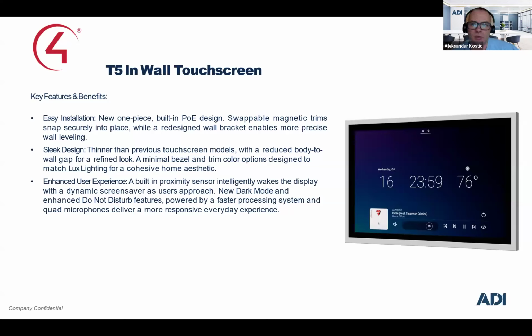You can order T5 in two main colors, black and white, but you can additionally order an extra frame in some other color to match your interior design. At this moment, those frames are available only as plastic frames, but we expect to have metal ones in the future as well. So just have in mind that if you use metal frames later, you cannot use Wi-Fi connection from the in-wall touchscreens. But generally, in most cases you use wired connectivity, and they are PoE like T4. So you do not need any additional power supply for them if you have a PoE switch.